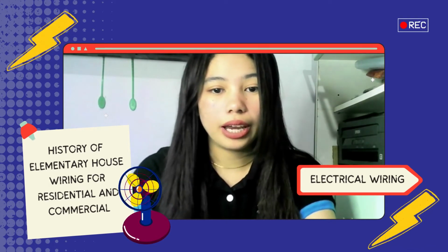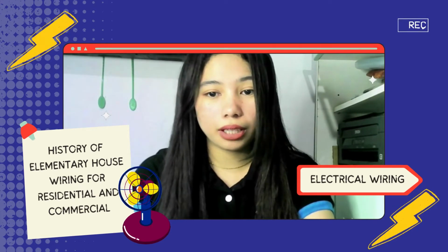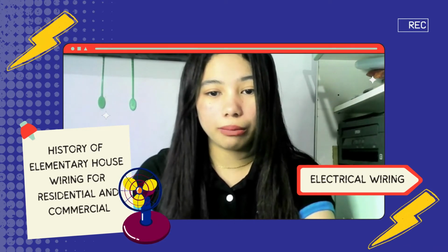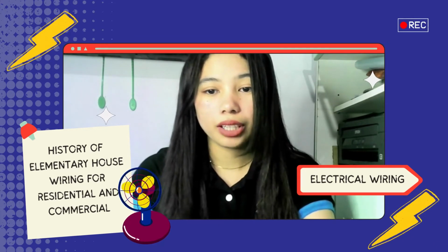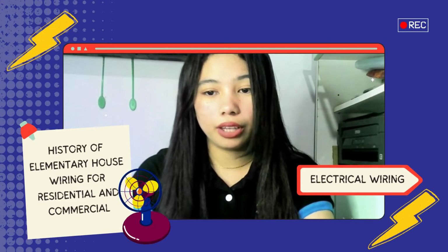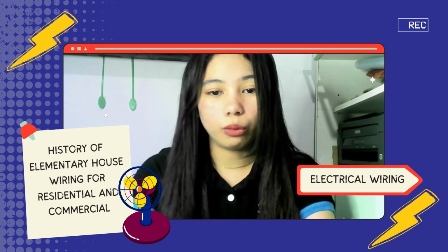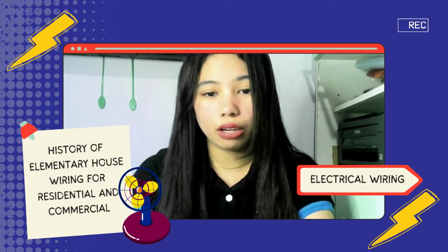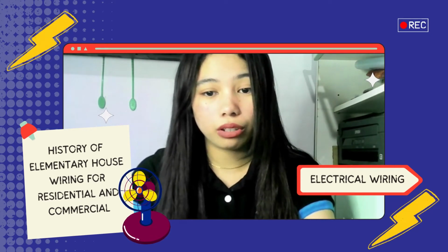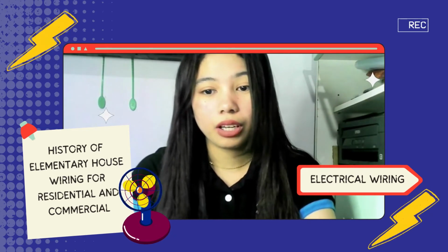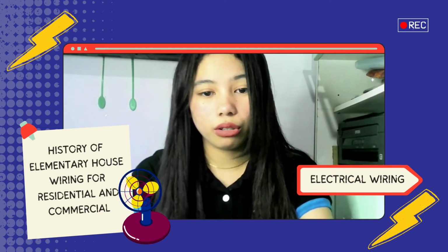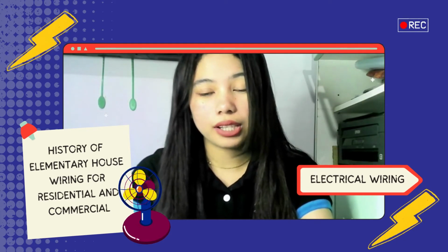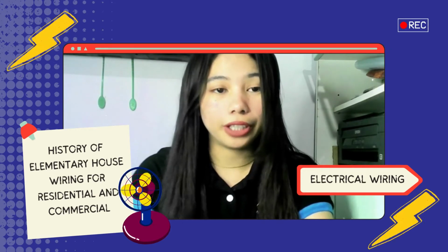with rag wire. In the 1930s, a quicker installation method was developed. Non-metallic sheathed cable was born, which incorporated a rubberized fabric coating sheath. Much like knob and tube wiring, the hot and neutral wires were run together in one sheathing. It also had no ground wire, but its development would eventually lead to major innovation. Early cable, however, also has an expected lifespan of about 25 years, and where it is still in use, such installations need to be upgraded.